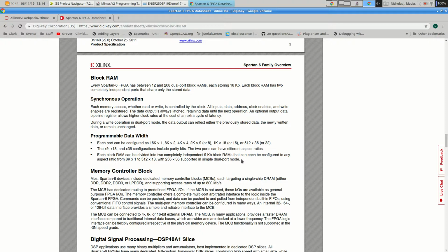And that's different from chip to chip. And the way that you actually load in the ones and zeros to set up particular routing and so on, that's all secret. All right, that's all closed proprietary information for the vendor. Which is why we can't write our own software to program FPGAs, so you have to use software from the vendor or someone working with the vendor. But all the other information other than that level of detail is in these data sheets.